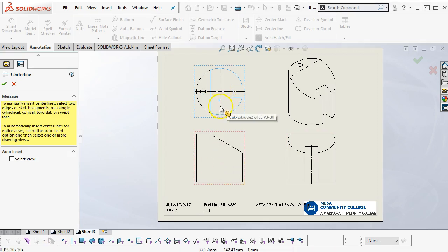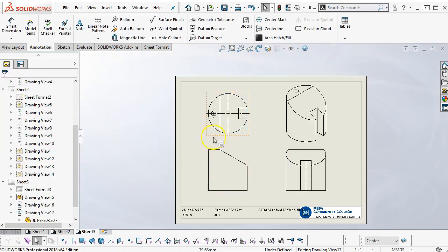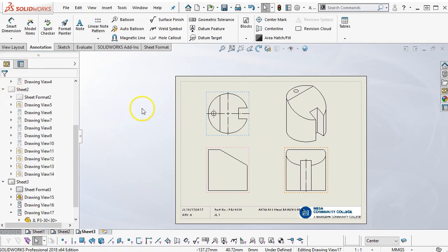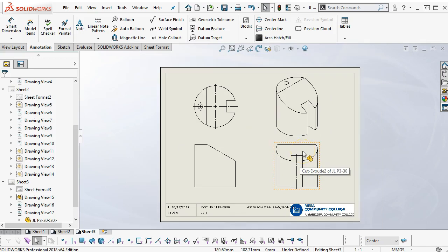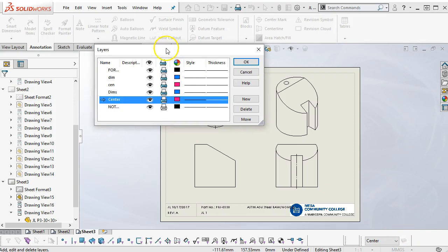So let's see, I got the face. Let's double check. Alright, so I'm still in center line, so that's not going to let me select. I was asking for selection. We'll go over change, and apparently in making all those adjustments, we carried over the new sheet format into the old sheet format for the layers, so I'm going to have some duplicates. If I really wanted to correct for those, whichever one's going to be the current, I'd go back into layer properties and delete those out.